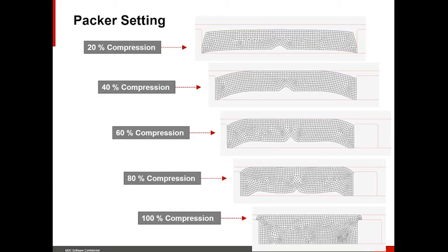In this compression load case, global remeshing is used to resolve the element distortions. Here, the mesh at 5 different loading levels is shown. As can be seen in these figures, all the meshes have proper element shapes without distortions, thanks to global remeshing.